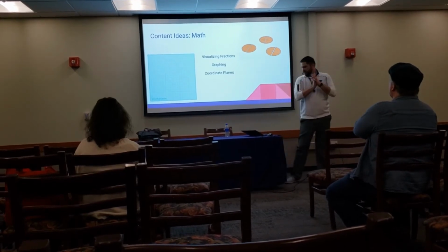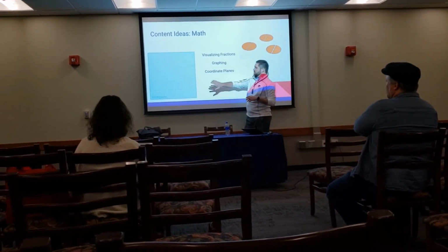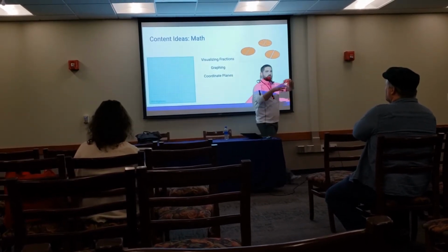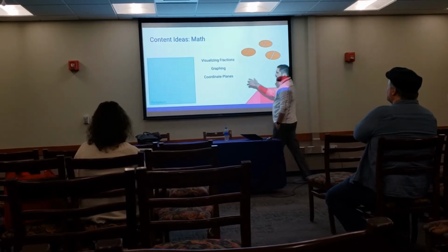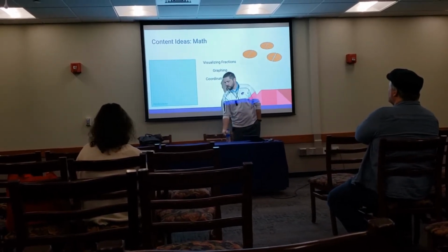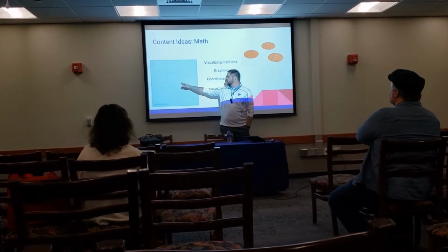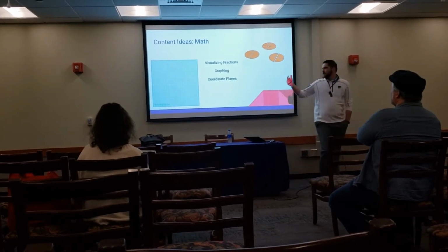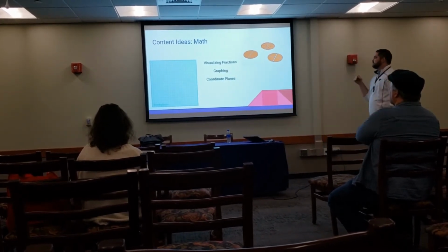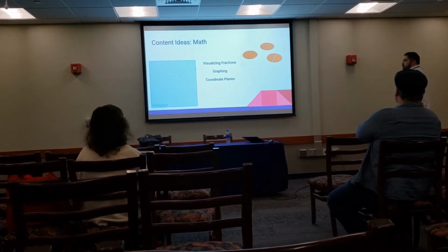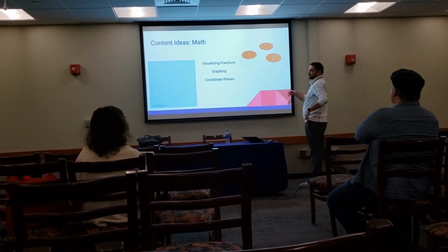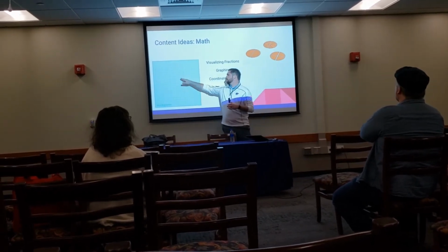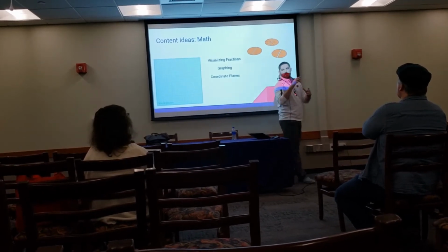And finally, coordinate plane. So in Tinkercad, we start with something called the work plane. And this is just the base layer that students build on. And it's got a grid to it. You can change the grid however you want. It can be big or small. It can have a 1 millimeter gap between the lines, or it can have a much bigger gap if you want, or much smaller. But students can use this to plot different areas like they would on a coordinate plane. And based on those plottings, build a shape. So if you give the kids a set of coordinates, if they're able to go in and put those spots or connect those dots, then they can go in and build a shape based on that.